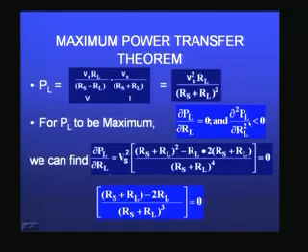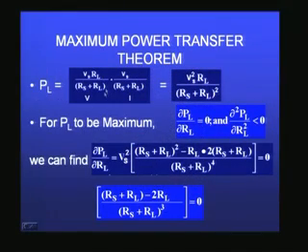Okay. Now how do I get this? How do I say RL is equal to Rs? Is there a way to prove it? I have just briefly taken a simple way of proving it. PL, the power output, is voltage into current, that is the definition of power. What is voltage in this case? Vs into RL by Rs plus RL, because we have already seen RL and Rs provide a potential divider. The voltage across RL is the total voltage multiplied by RL divided by RL plus Rs. This we have already seen, that is the voltage.